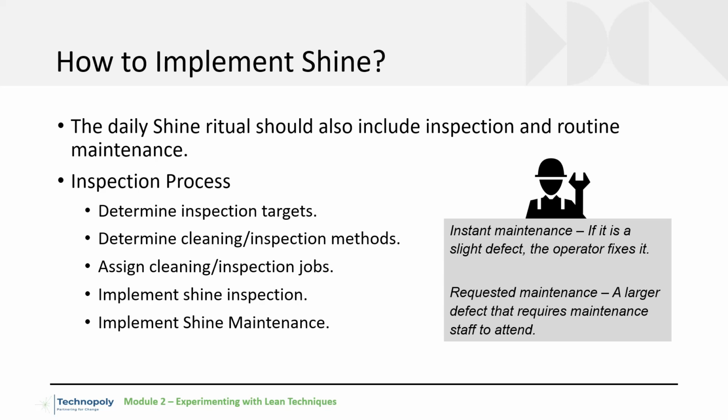Fourth, implement shine inspection. Remember to use your senses when inspecting equipment. Look for oil leaks, wear, etc. Listen for changes in the sound of the machine. Try and detect unusual odors. Try and detect unusual vibrations in the machines.